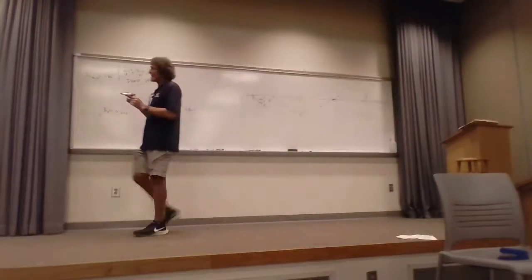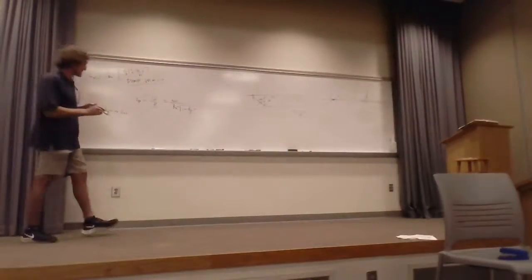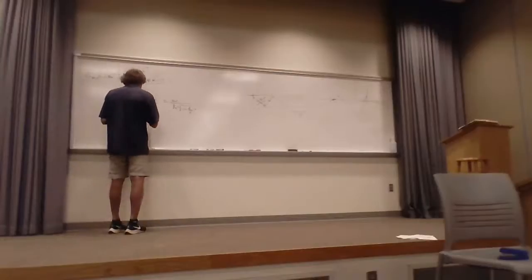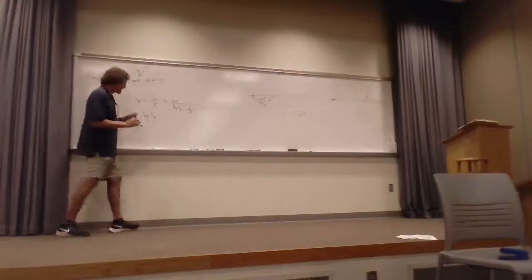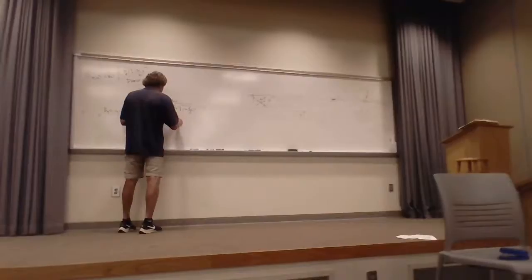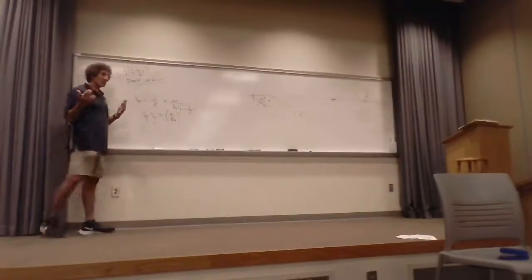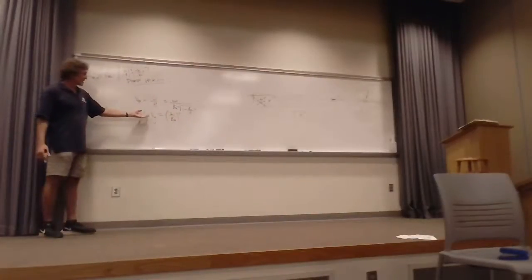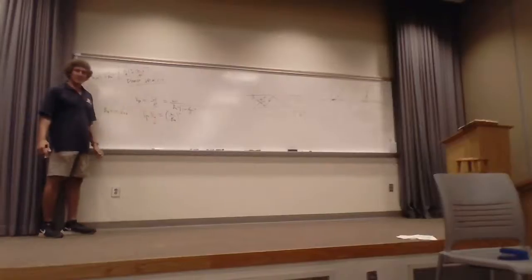So phase velocity has nothing to do with energy, but here's the thing. Phase velocity times group velocity, or velocity of energy, will always be equal to omega over beta unguided, squared. So when you have the phase velocity, you take omega squared over beta squared and divide that by the phase velocity, you get the group velocity.